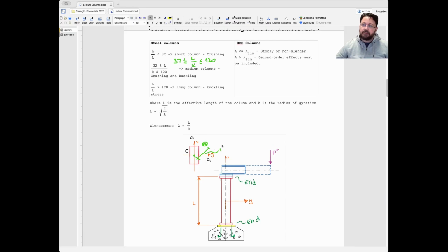So whenever you see radius of gyration and think it's something weird, no, somebody just came up with the idea that I want to simulate the mass distribution of an area, of a segment, with respect to a Cartesian coordinate system, but instead of using the full geometrical definition of the area, I'm using just a particle. This particle has a mass, and the radius of gyration is the distance from the center of that Cartesian coordinate system to the mass. That's it. That's the definition of it.